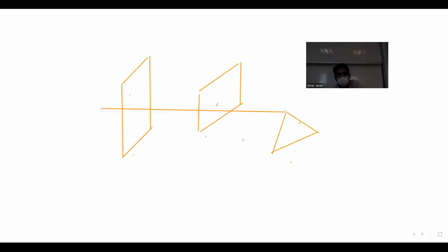If it's a rectangle, it's in the middle. If it's a circle, it will be in the middle. If it's a triangle, no, not in the middle, right? It's at b by 3. I think everyone understands. So if you make a beam like this, you cannot say that your neutral axis is in the middle. For sure not. It will pass through the centroid. Okay, I think I have made my point. Stress in x equals minus My over Iz.